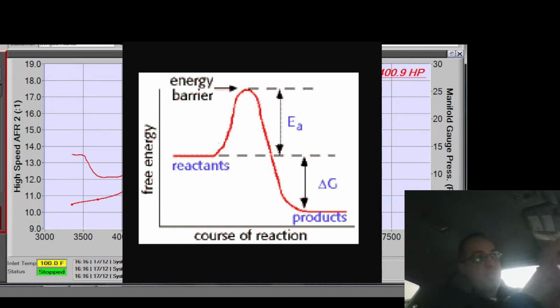So it blows on the contacts. And the same thing happens in the cylinder. If I got too much movement in there, and there's not enough density, and there's not enough spark energy, I can have a misfire. I can not take that activation energy from the energy of the combustion and transfer it to the next one, or I may not even be able to ionize the molecules between the two electrodes on my spark plug, because there's just too much movement there, too much going on, that per unit time I end up needing way more spark energy than I currently have.